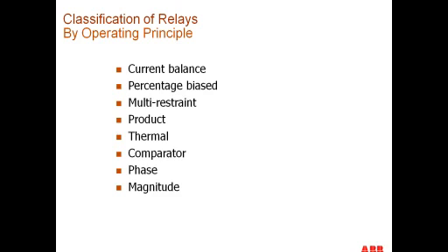There's percentage biased relays, multi-restraint, current differential relays, product relays, thermal relays, comparator relays, phase and magnitude comparison relays. So there's lots of different ways we can classify relays, and again, each one of them has a certain purpose in life as far as the protection engineer is concerned.